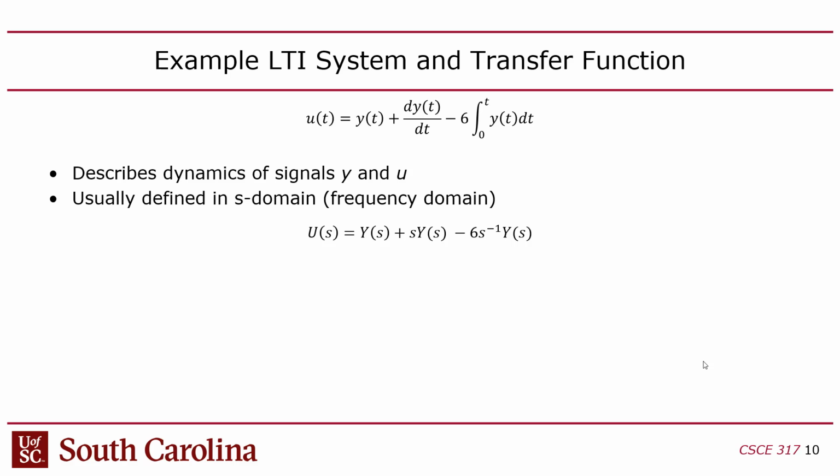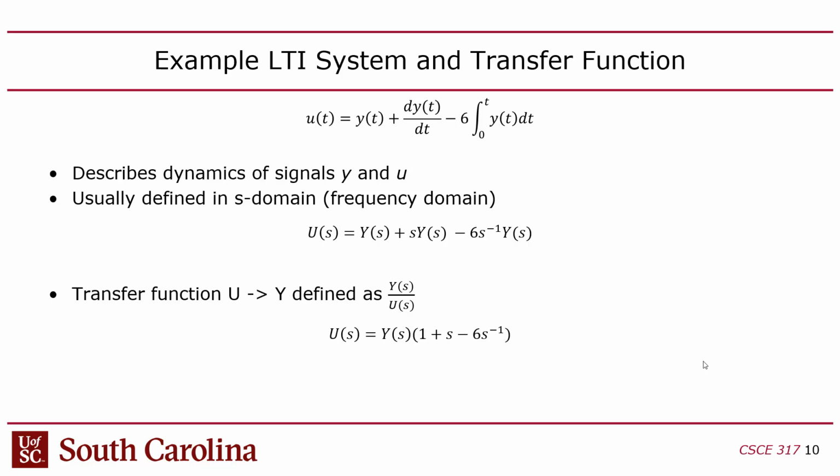And then you're like, well, okay, but that's not a transfer function. How do I make this a transfer function? Well, you have to decide what the inputs and what the outputs are. Do we want u relative to y or y relative to u? You can go either way, depending on what's going on. In this case, I'm assuming u is the input and y is the output. So my transfer function has to be y over u, right? Output over input. And so you have to do some algebra here.